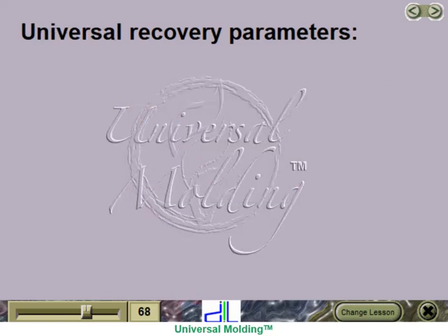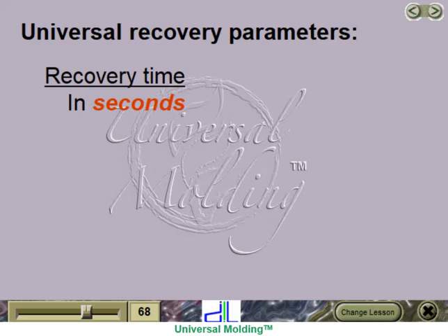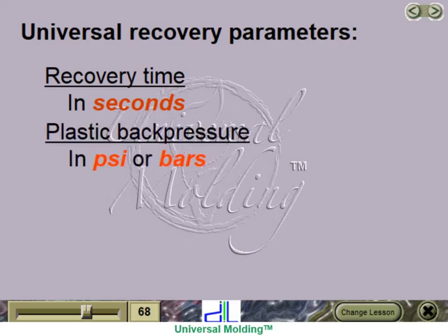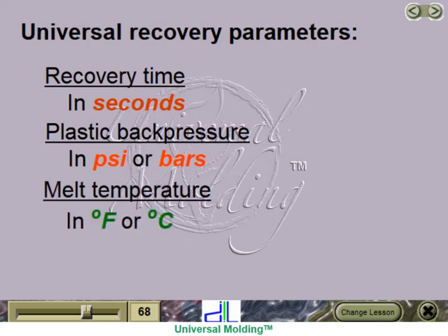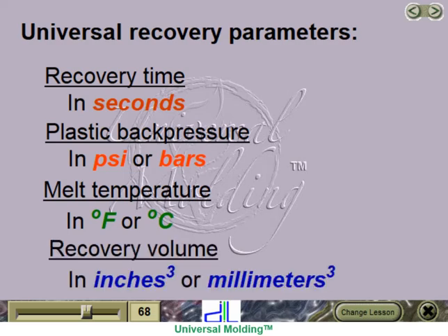Universal recovery parameters. Recovery time in seconds. Plastic back pressure in PSI or bars. Melt temperature in degrees Fahrenheit or degrees Celsius. Recovery volume in cubic inches or cubic millimeters.